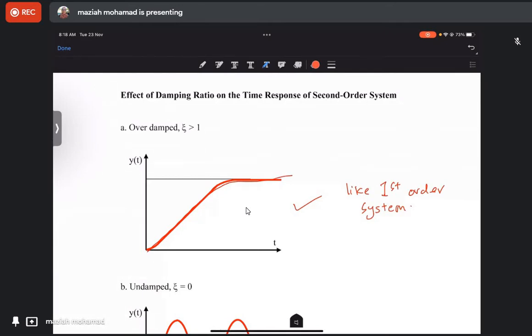You will feel the bump, right? The energy of the bump will transfer to your body, so there will be less comfort in that. Because the energy is damped very fast, the energy is transferred to our body. So it relates to ride comfort in a car. So that will happen if you choose zeta damping ratio bigger than 1.